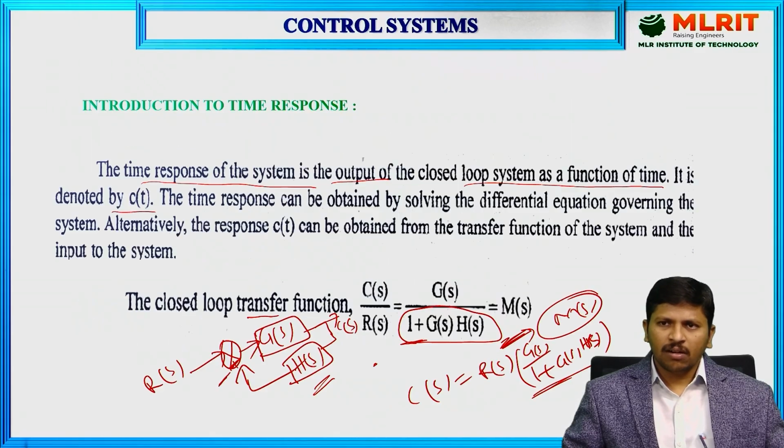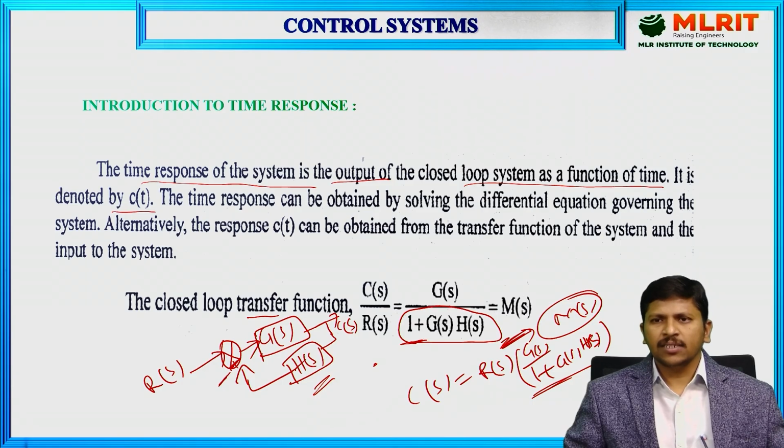This is about the transient response, just a simple introduction to transient or time response analysis. In that, we covered how many parts are available in the time response, the transient response as well as the steady state response, and how to calculate the time response from the S domain system output: we apply the inverse Laplace transform. All these we learned in today's lecture. Thank you.